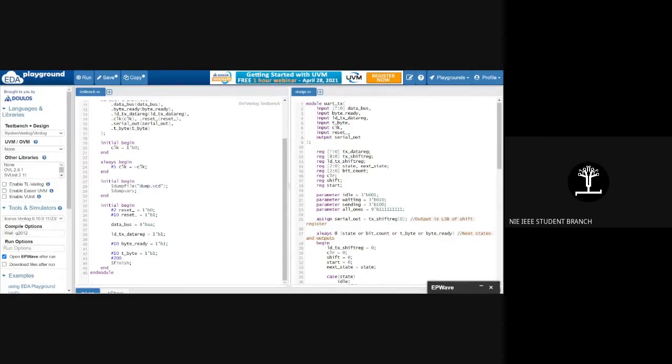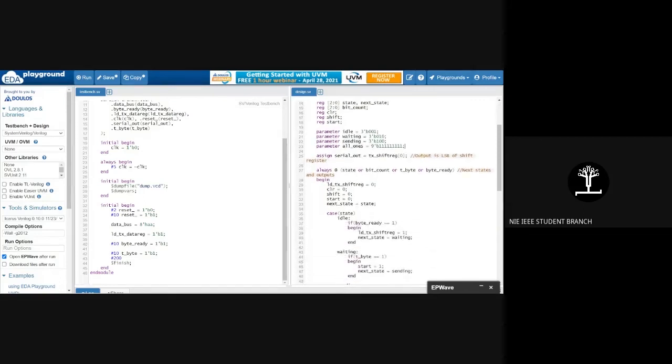So what this does is, once you have transmitted the data packet, the whole thing, we backfill with stop bits, and the stop bit will go low when you're sending another packet. But if you're not sending another packet, the whole shift register gets filled with ones. So to fill all that with ones, I use a parameter. That's why I use it.